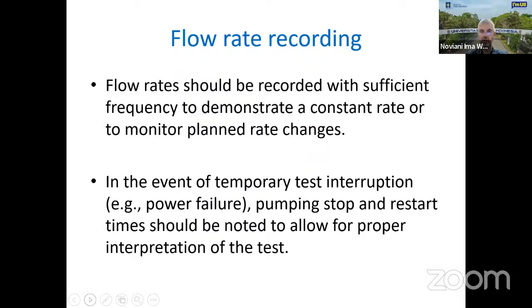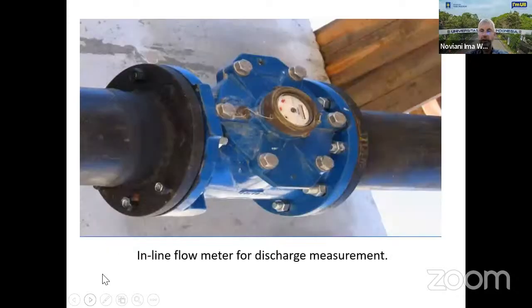So how do you measure flow rate? Okay, flow rates are measured with what is a flow meter. And they come in different sizes. This is a fairly big one. You can pump maybe 1,000 liters per minute with this type of flow meter, and you can still measure. So bottom line is, when water is flowing, there is a wheel inside here that is turning. Actually, 3 wheels. One is turning slowly, one medium, and one is turning super fast.